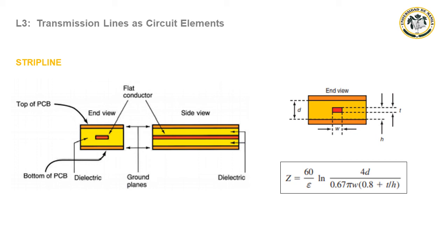Meanwhile, a strip line is a flat conductor sandwiched between two ground planes as shown. It is more difficult to make than a microstrip. However, it does radiate as microstrip does. Radiation produces losses. Even tinier microstrip and strip lines can be made using monolithic, thin film, and hybrid IC techniques. When these are combined with diodes, transistors, and other components, microwave integrated circuits or MICs are formed.